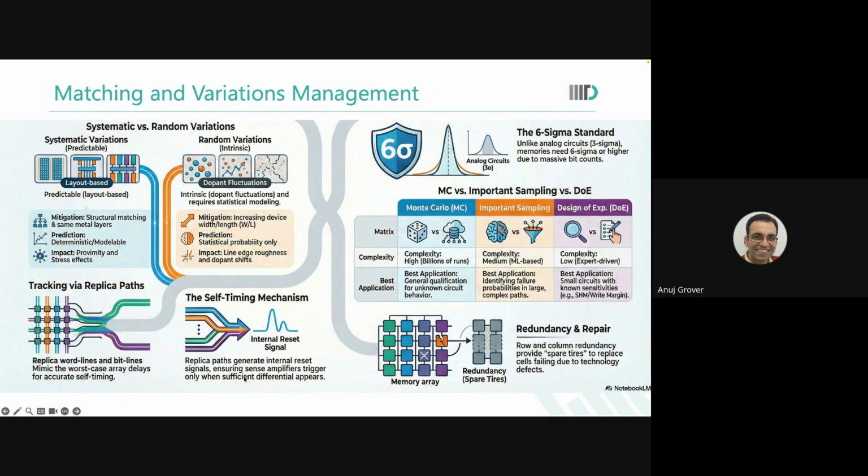We already talked when we were talking about IO circuits, we talked about so many race conditions. We talked that word line precharge, bitline precharge has to turn off before the word line gets selected. There are so many race conditions in memory design anyway. Are you realizing we've been talking about verifying race conditions since the beginning? So it's not new. Race conditions are handled by design, and this you can handle. Dynamics are saved, power is saved.